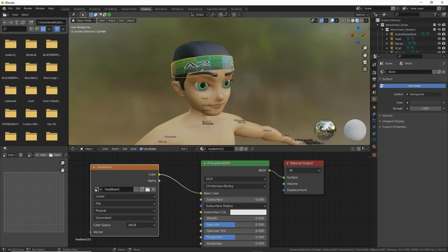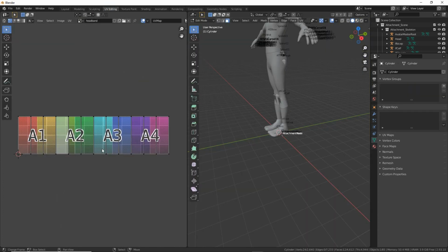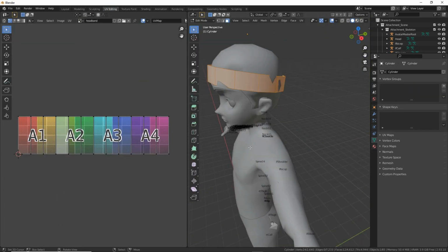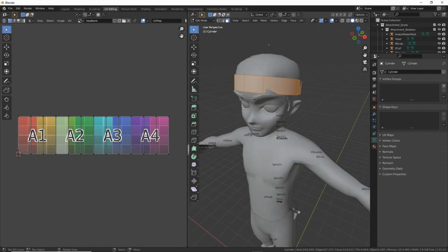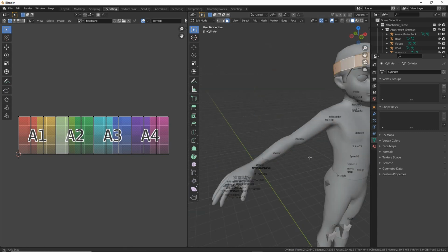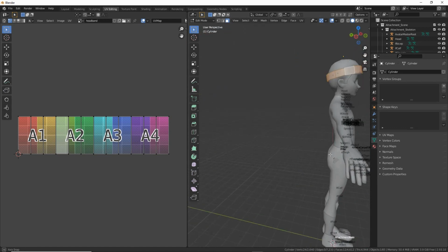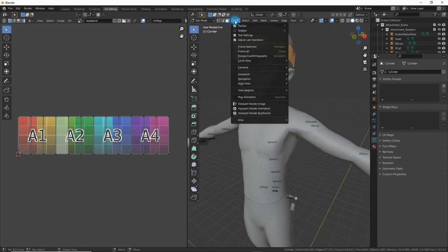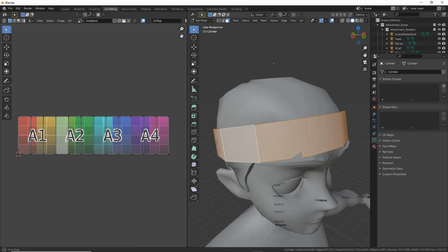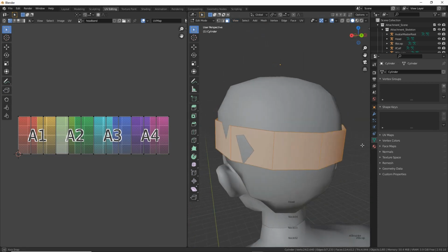So for the UV map, we want to go into UV editing. So that's the UV map. The object is already automatically set up for editing. So let's just focus on our object to make this easy to manipulate the scene, because it's a bit wayward at the moment. So for that, view, frame selected. What this will do is shift the object to the center of the screen so that we rotate around it.